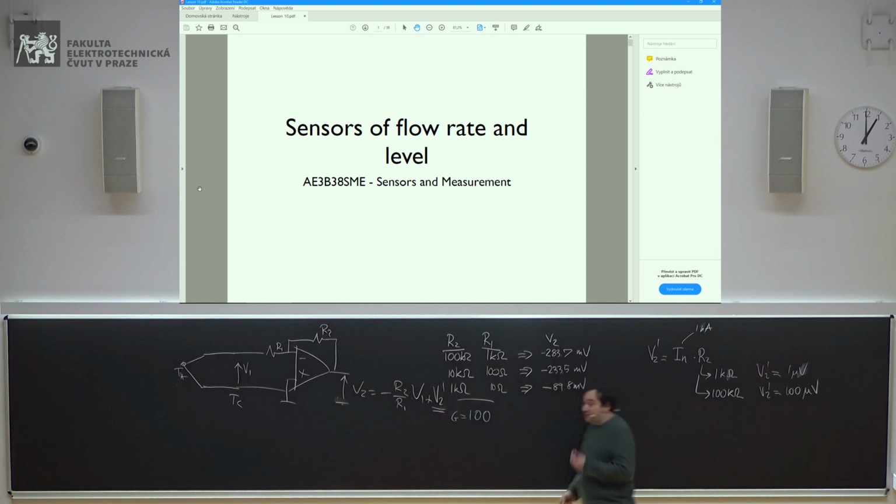But the difference is so small. It's 100 microvolts against 1 microvolt, which is really, really a small difference. Here you observe a difference which is much bigger. You go from 90 millivolts to 284 millivolts. So you have roughly 200 millivolts of difference. So definitely this difference given by the bias current cannot justify the difference we observe at the output. Because here we have a difference of 100 microvolts, and here we have 200 millivolts. We are observing a change in the output which is 3 orders of magnitude bigger. So yes, the phenomenon itself is true, but once you plug in the numbers, no, that is not what causes the change in the output we observe.